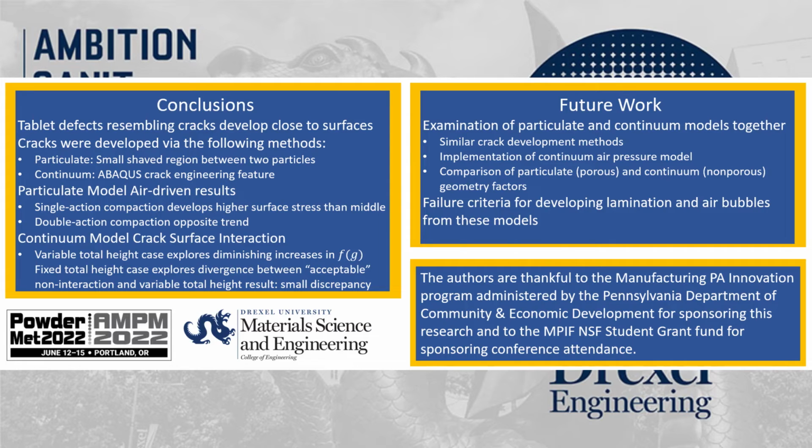The continuum model assumptions include the axisymmetric high aspect ratio compact with a single defect forming. Both models utilized elastic materials. Future work in this area could include merging air pressure effects with the continuum model and comparison of defect formation methods for models. Developing a crack engineering feature in the periodic model would allow direct comparison of stress intensity factors between the two models.